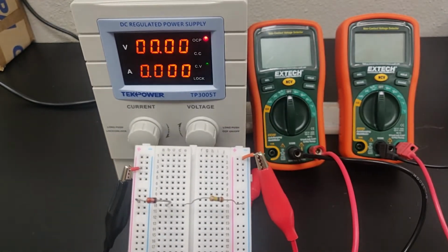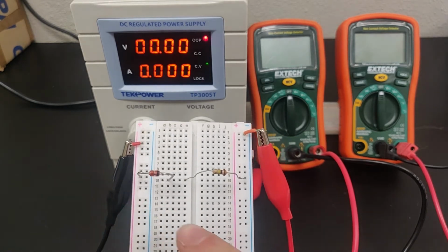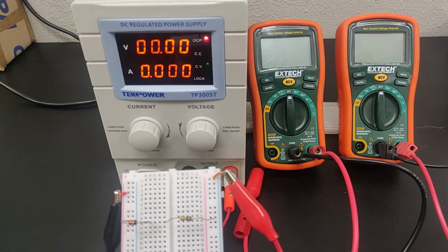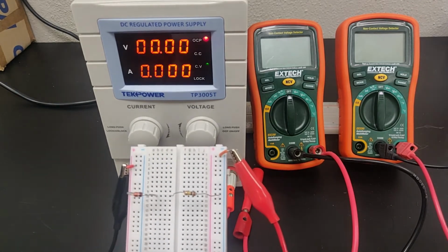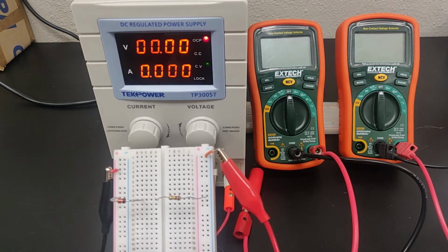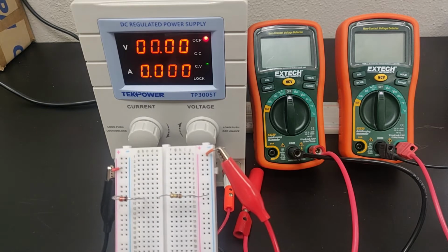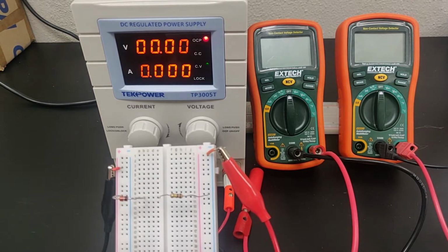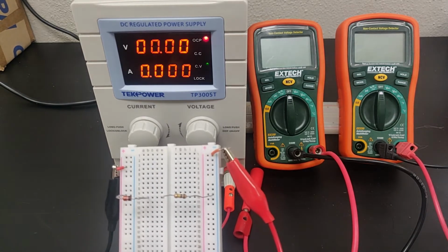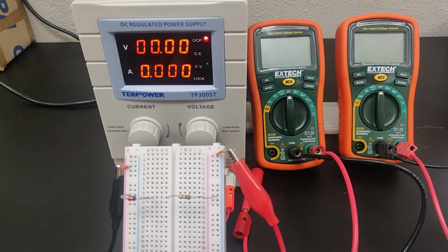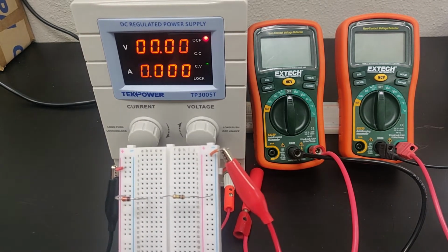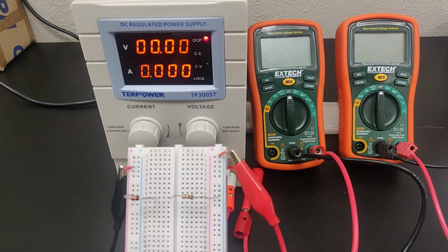So to do that, we're actually going to be using 2 different resistors. If we look at the manual, looking at the procedure, we're asked to initially get a 100 kilo ohm resistor and go through a DC sweep of around a volt to 10 volts on our power supply, and then replace that 100 kilo ohm resistor with a 100 ohm resistor and go through the sweep again.